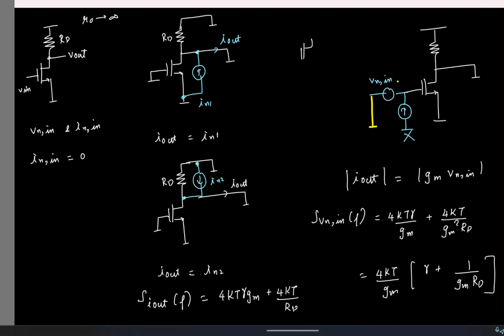No, let's say I have some current here and I'm trying to find the output current. We cannot compute current. It's basically an open circuit, it's infinity, right? This voltage will become infinity, so the transfer function itself will become infinity. So the power spectral density of the current will become 0. That's why you don't have to calculate the things for noise current. In simple terms, if the input impedance is infinity, the current is 0.